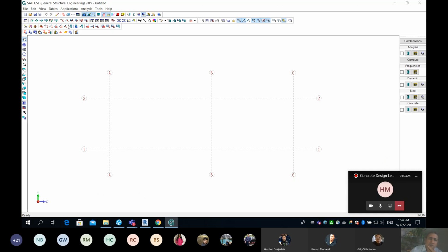If you look at the toolbar on the bottom, on the top left, and again, you don't have to memorize, because those toolbars, just like any other software, have something called a tooltip, which means if I leave my cursor for a second above the icon, you can read, it says here add. If I leave it for a second, it will say add joint, or you can use the hotkeys Shift plus J. And what this does is simply allows you to add joints.